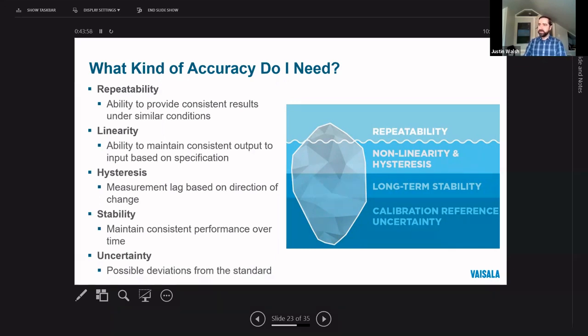Stability refers to the drift in accuracy of the sensor over time. Most, if not all, sensors drift in that their measurement error increases over time. This is why we calibrate and adjust sensors, and poor stability leads to more cost and effort.